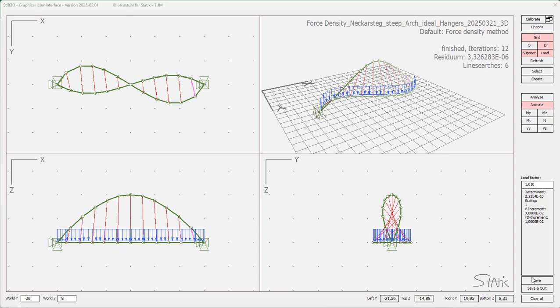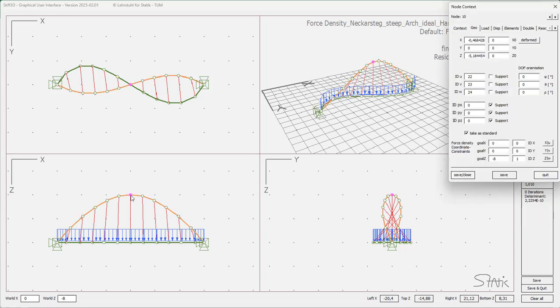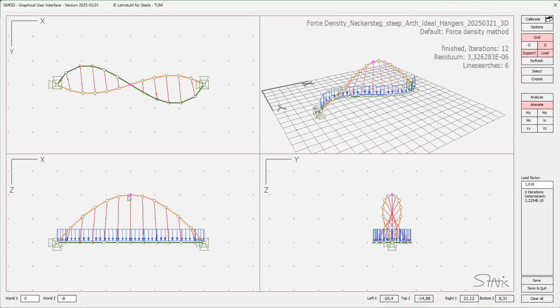Last but not least, it remains that we check if we are really successful. Remember, the goal was that the apex should be at z equal to 8. Visually it seems to be okay, but let's take a closer look, double click at the node. We see here the original coordinates of this node. We had been starting with -5.81. If you press default, you can see the actual values, which is exactly what we like to achieve, -8 for z. That is okay.